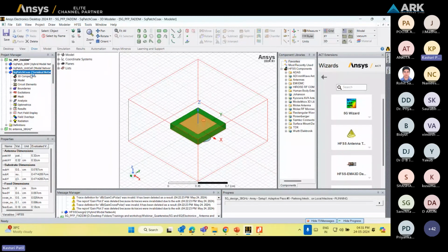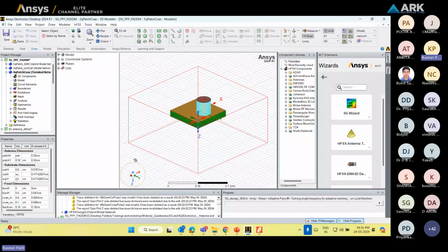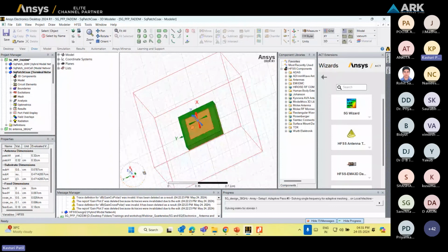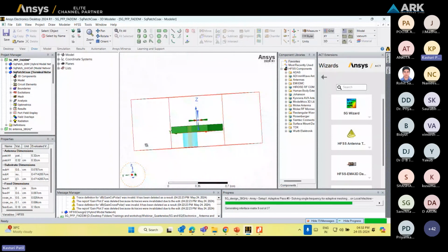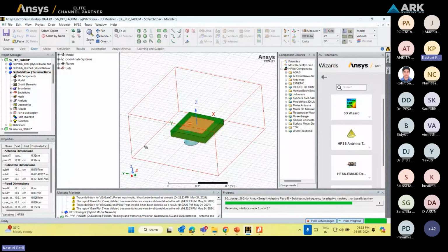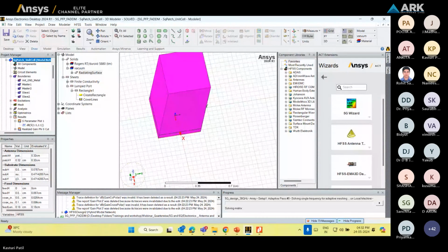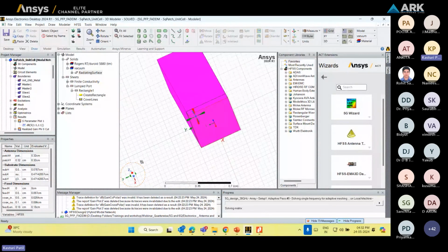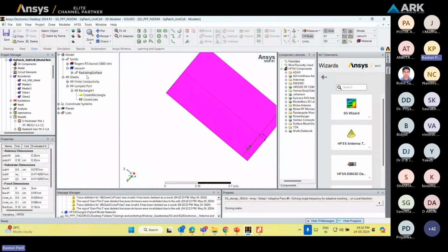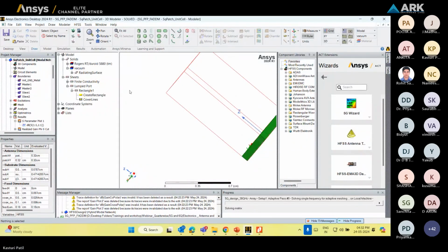In this actually three parts are there. First, design a single element antenna using the HFSS tool. So this is the coaxial feed antenna I have designed. How to design that, I will tell quickly. After that, I have created the unit cell for this. So this is the unit cell. At the bottom you can see the antenna is there.